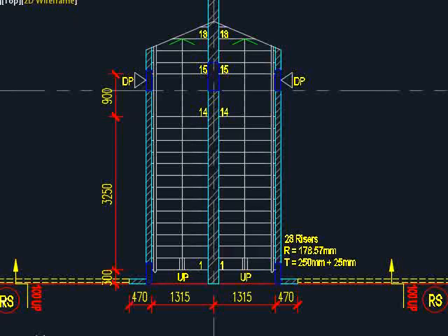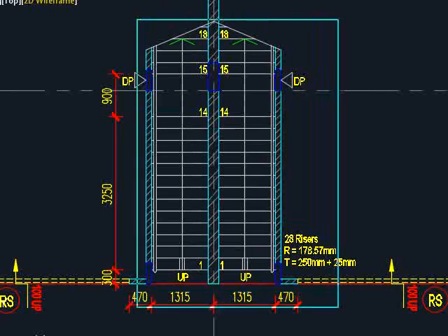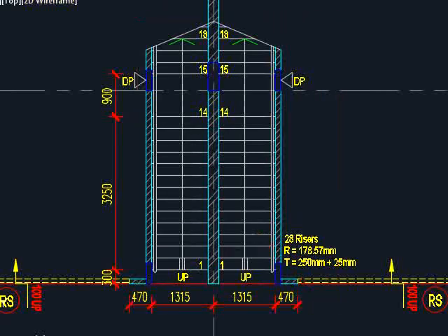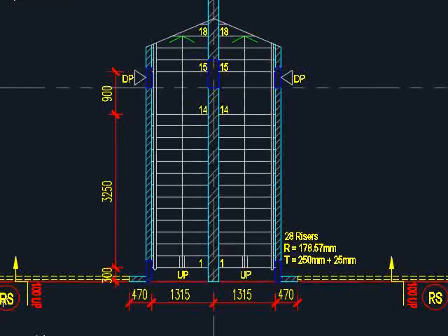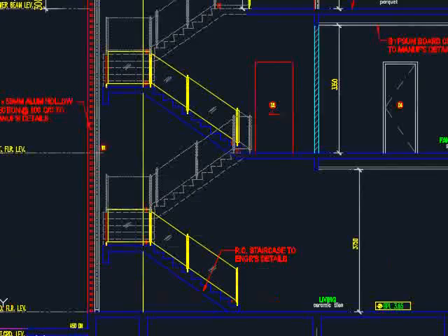You need to make sure the shapes which you view from the side of the staircase are in line with the plan view as given by the architectural drawing. In the case that the information is not in line, you should cross-check with the architect for further clarification. Normally, the architect will indicate to you which parts of the staircase are to be designed by the engineers, which in this case, the RC staircase is to be designed by the engineers. And the handrails are not the RC part, thus you don't have to design that.